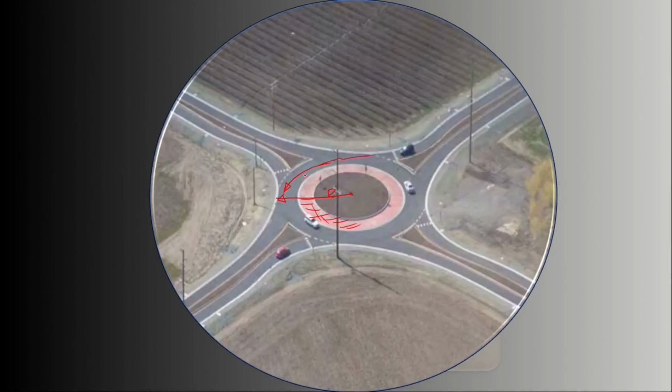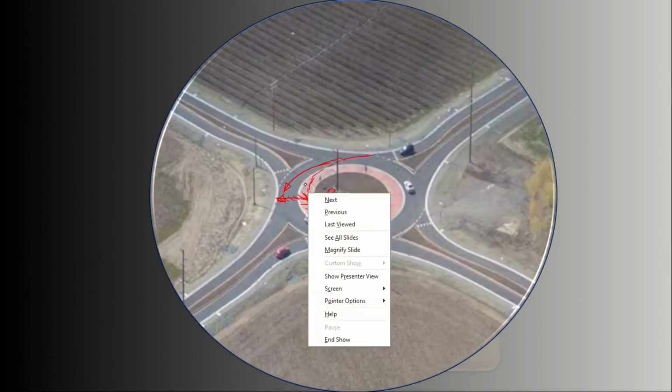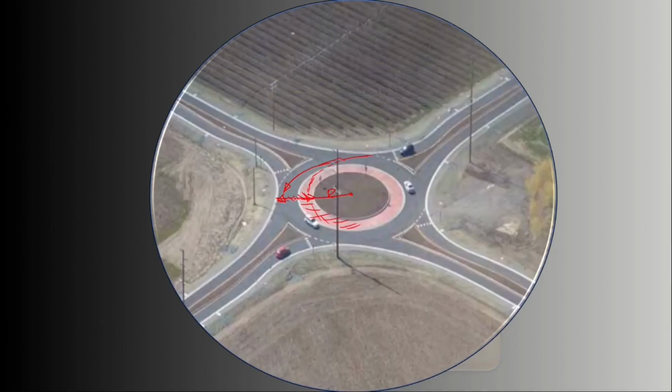But especially in urban areas, if we make their circulatory roadways wide enough to accommodate the whole width needed for large vehicles, then the center island will get too small to dictate enough deflection for entering traffic to slow down. Let's make a comparison.